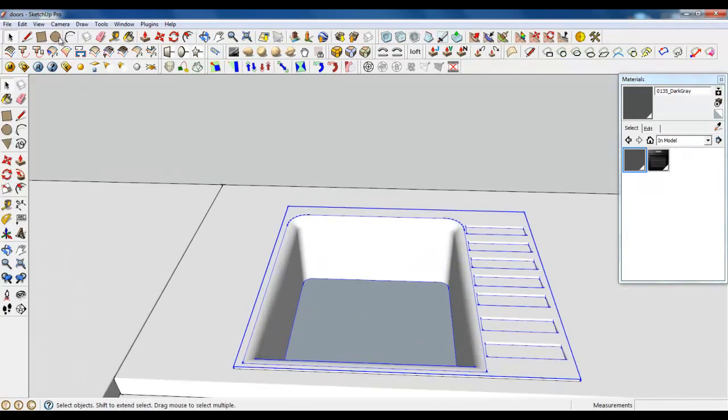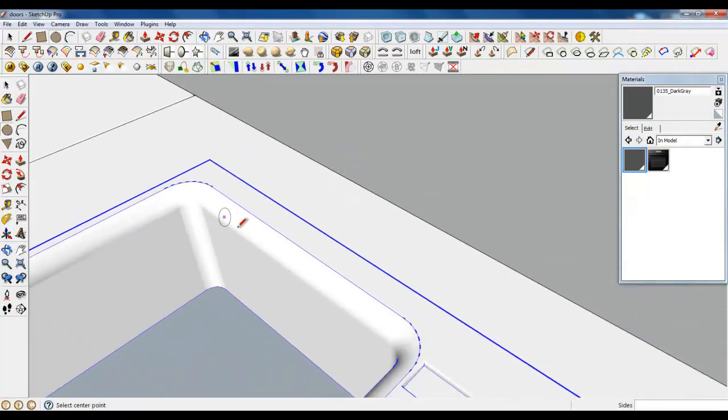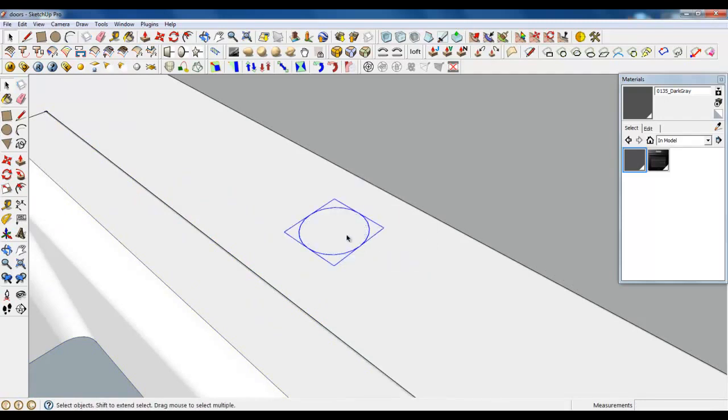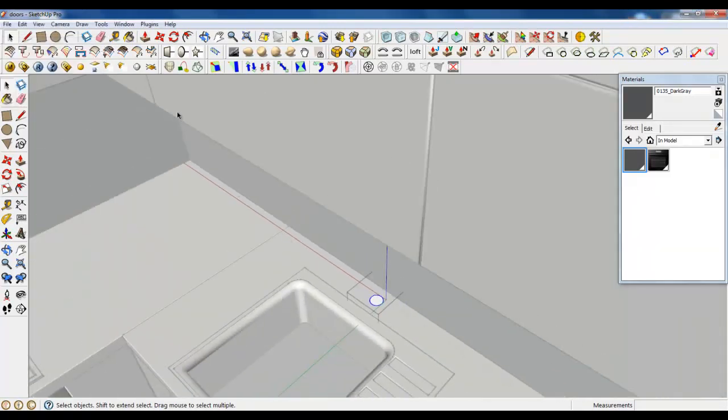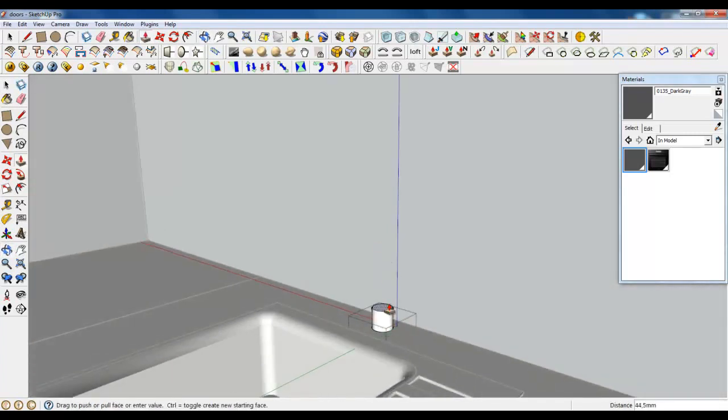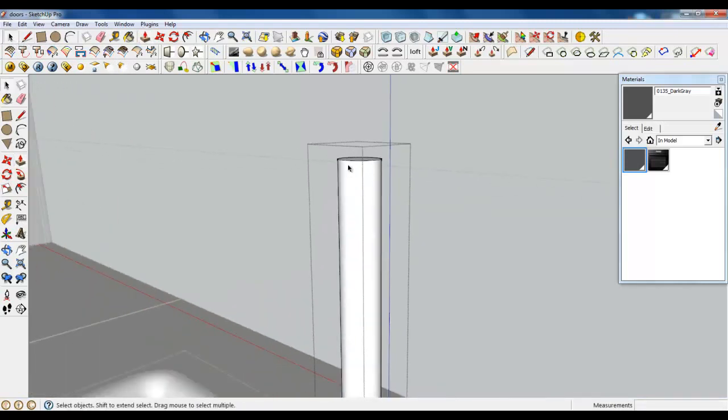A tab creating is really simple also. So firstly, create a circle, type in 20 millimeters radius, and make a group. Also give it more segments. Let's type 15 and drag it. Well, it's good now. It's 250 and enter.